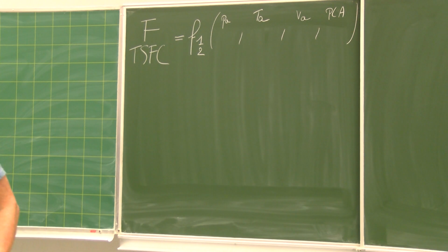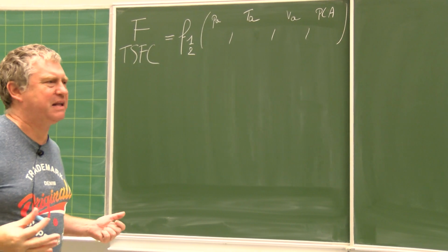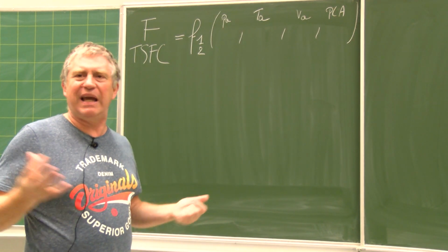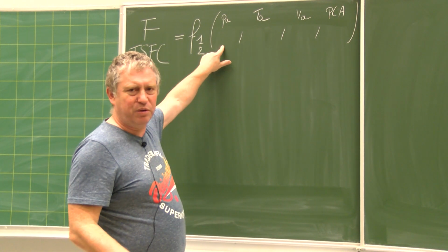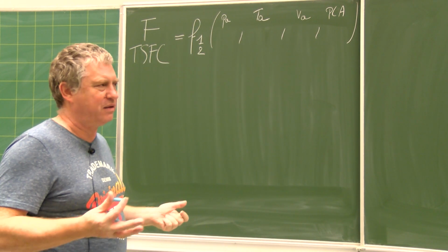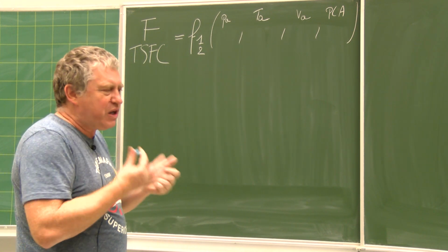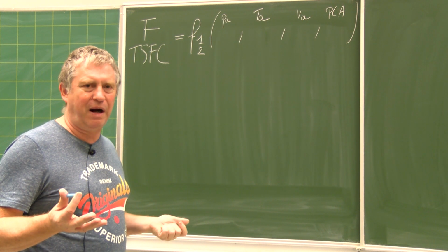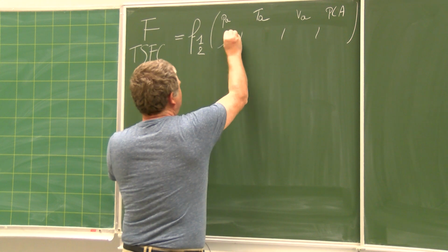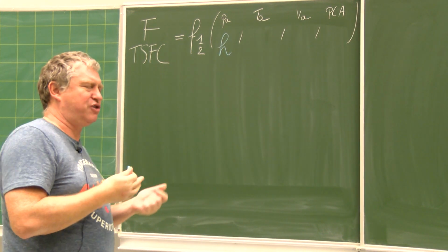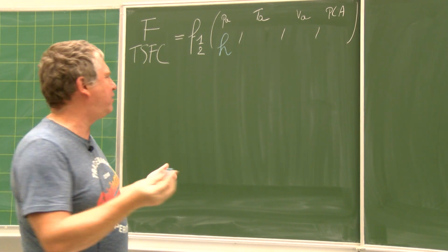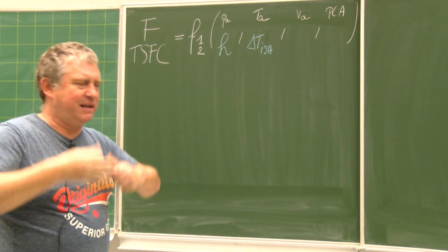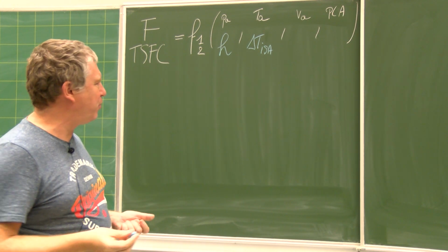And we can also define other 4 parameters, whatever. We could say the temperature of the oil in the second bearing. It is also a parameter that we could put there. Whatever the parameters you want, you can choose them. You have just to have 4 independent parameters. And very often we will more speak in altitude. This is the pressure altitude that we call altitude. The delta T compared to ISA, which is atmospheric temperature, OAT, whatever you want to call it.